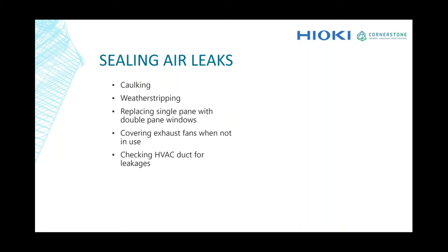The exhaust fans can be covered, and of course the HVAC duct leakages. For that we have a separate test, where again we use a blower door fan to pressurize the HVAC ducts and smoke for finding out the leakages. So yeah, that's pretty much it.